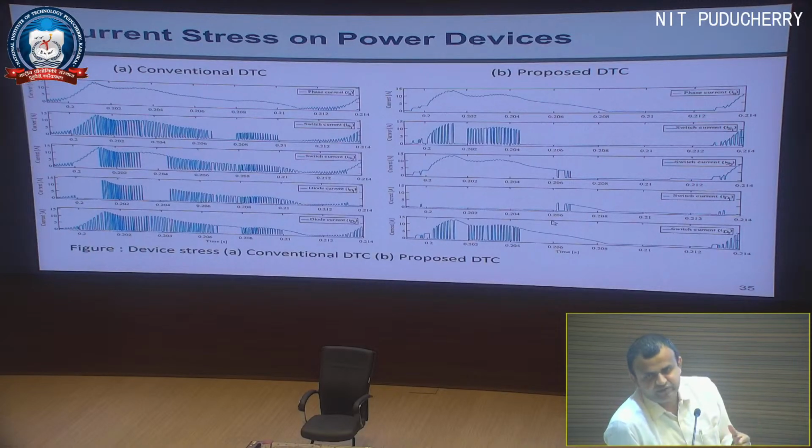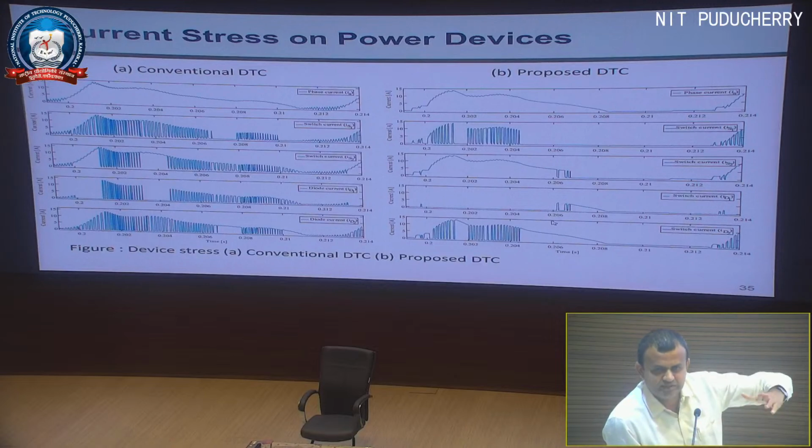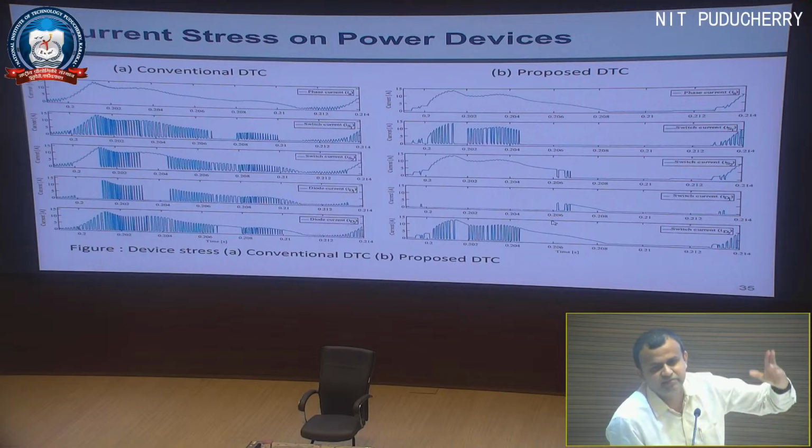If I were satisfied with low frequency, I would have used only thyristors and been happy. The moment I say I am going for high frequency, what does it indirectly mean? I am trying to switch on, switch off, switch on, switch off so many times in a cycle.